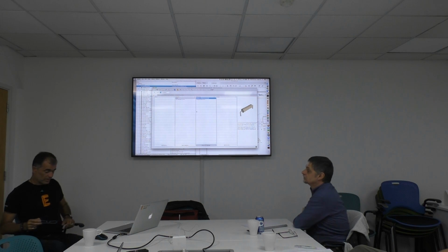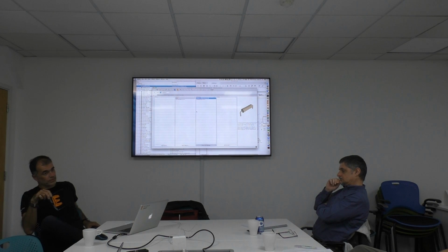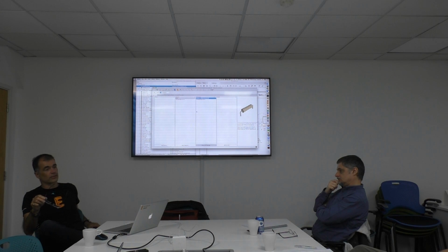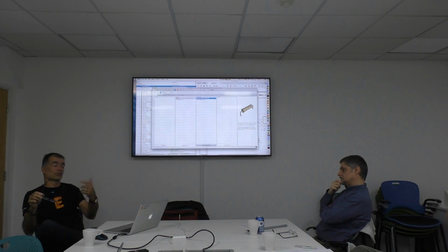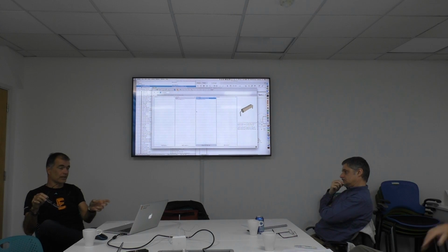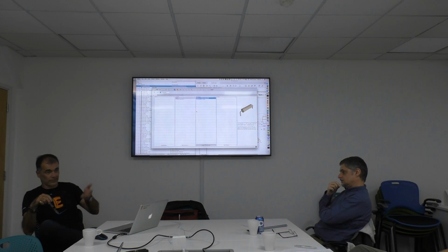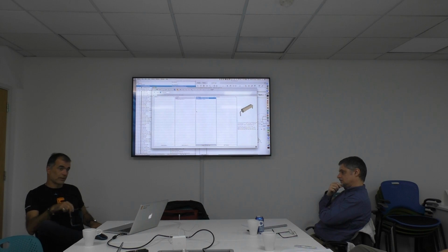The unique supplier part number is something you could work with by defining attributes. Our resistors have no values, so we say that's a resistor and you decide what it will be. Then you could also have the attribute, the MPN, and you have to fill in the attribute with the correct number. That's one option, or you really make a complete series of resistors with all the values in it.